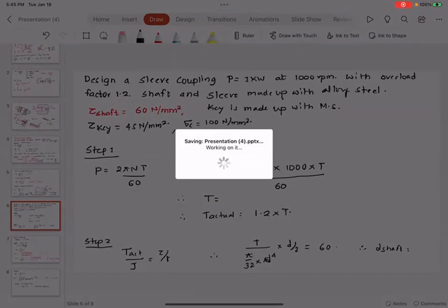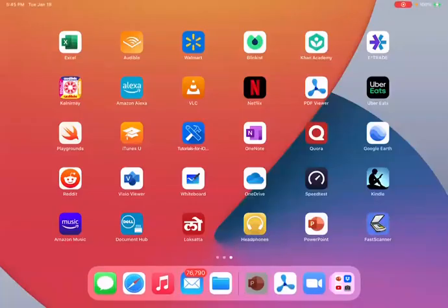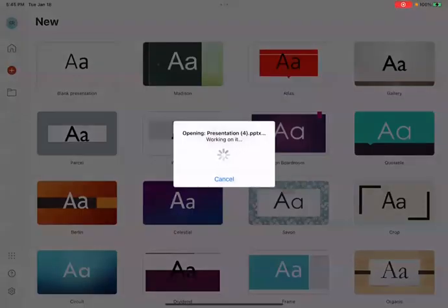Yeah, I could understand the different stresses, but in what cases would you use the rectangular versus the square key? It totally depends. I have used mostly square keys, but sometimes if the design requires it to be a rectangular key, there is a consideration that you do. Because most of the times, the key is like sacrificial, right? If you over torque, it'll shear the key. Yep. Okay. So for the square, yep, that's what I have used. Okay.